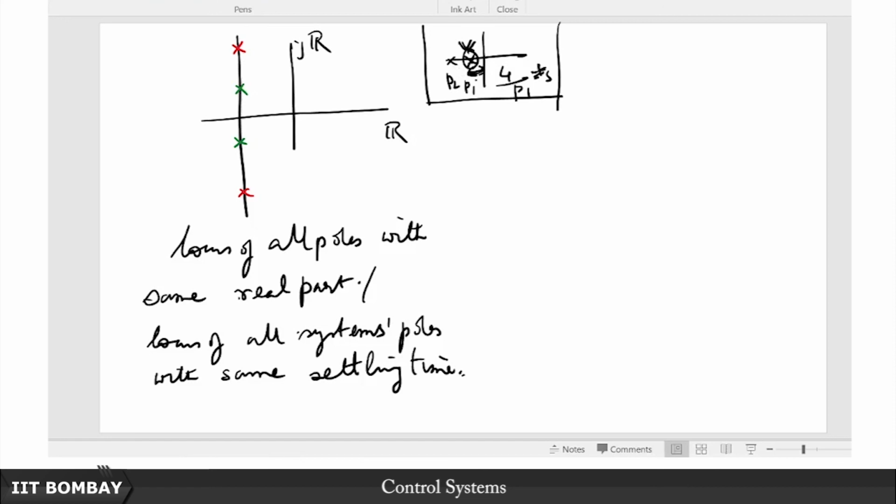So which is the one that should govern the settling time? It is the one which is closer to the origin, which is also called the dominant pole, because this is the rate determining step, this is the pole which governs how fast your system responds, alright. So keep that in mind. So even if you encounter an overdamped system, you can still define the settling time as a reciprocal relationship with respect to the pole location if you consider the dominant pole, okay. So hopefully that settling time discussion is now clear, and you also know the constant settling time loci here, okay.